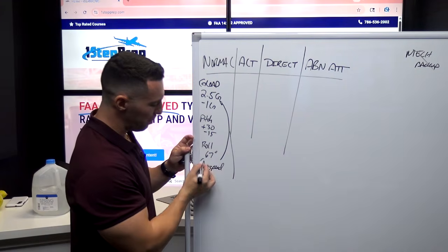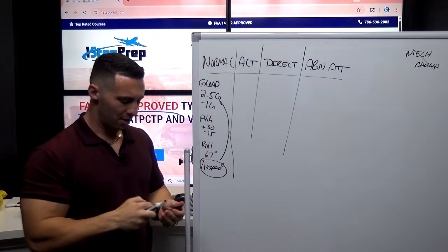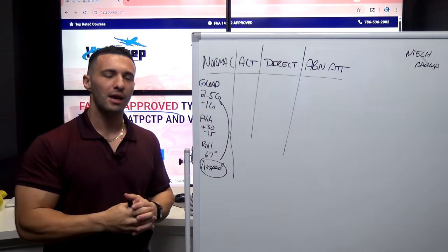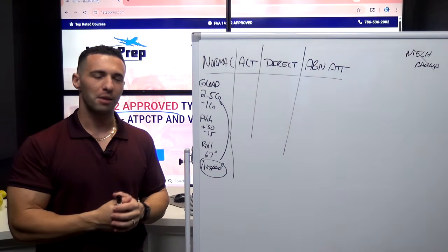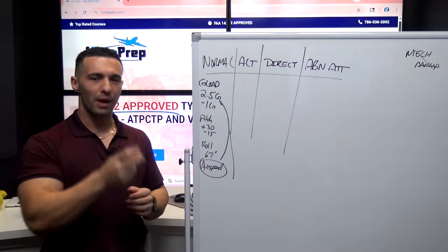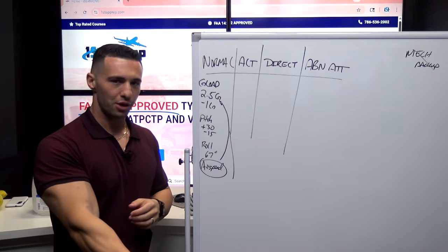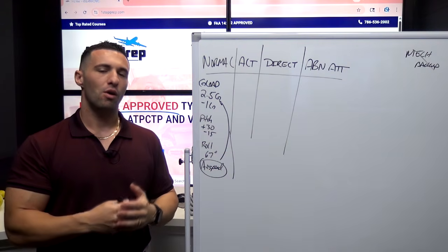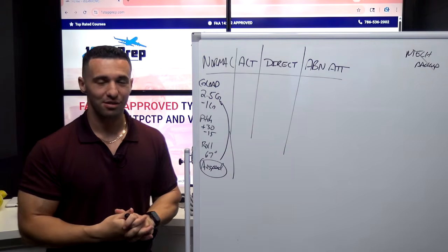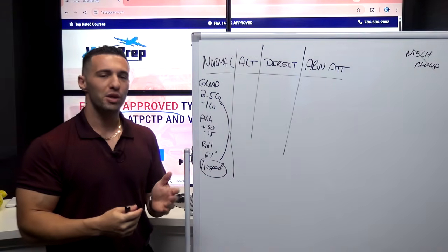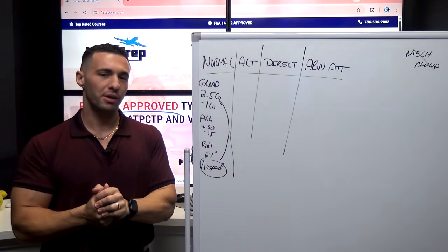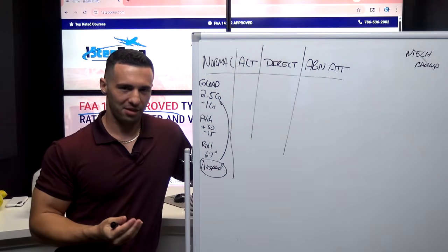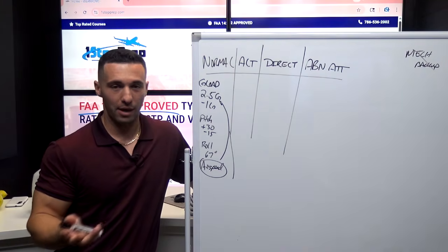What I'm going to say about airspeed protection that's very interesting, you may or may not know this, airspeed protection is one of the few protections that you can actually, to some degree, override. It's not completely overrideable, but you very much can grab the side stick and continue to push nose down and overspeed even deeper into the airspeed tape, all the way upwards of plus 16 knots. So you can go another plus 16, at which point the side stick will gradually begin to lose authority. And you may wonder, why would it allow me to do that? Why would I ever need to go another plus 16? And the truth is, hopefully you never have to do that.